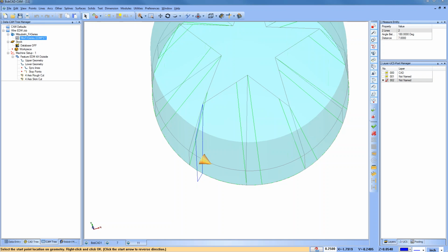Why not set 0 of stock to the wire start point? Linda, that's actually a very common thing to do as well. Set the wire start point at 0. Really, it just depends on your workflow, so you absolutely could do it that way. Usually, like a 2-axis inside shape, I'll set my 0 for my start point, but you could have multiple cavities as well. I didn't get into patterns in today's webinar, but sometimes you'll have multiple patterns, and your 0 isn't always where your start point is.